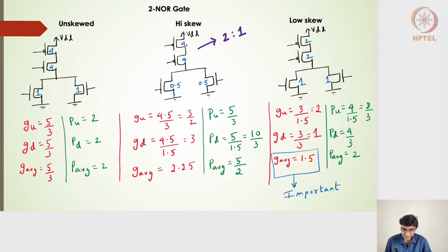The reason is that the two transistors on the PMOS side will give me an equivalent transistor width of 2. That's the reason why I need a 2:1 inverter as the benchmark inverter for the pull-up side of the circuit. For the pull-down side, 0.5 is the width of the transistors, and that's why my benchmark inverter will be 1:0.5.